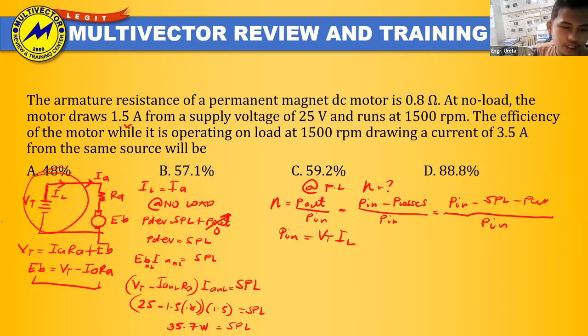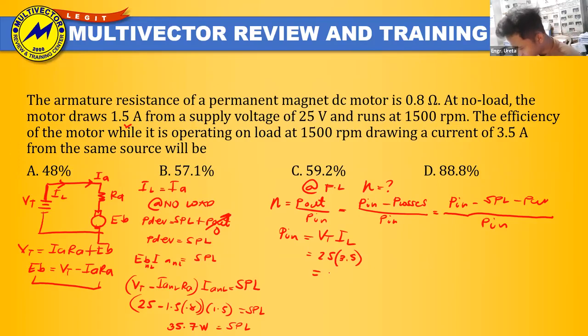Terminal voltage natin, 25 multiplied by IL. Our IL at full load is 3.5. Therefore, the input power is 25 times 3.5. Magiging sagot natin dito, yung input power natin is 87.5